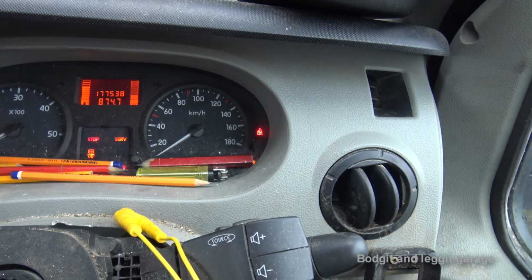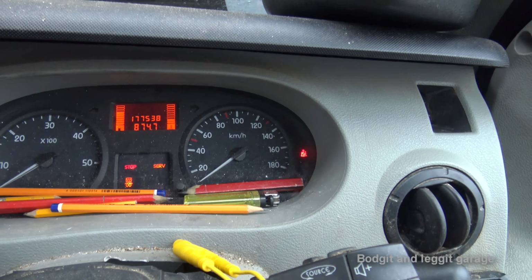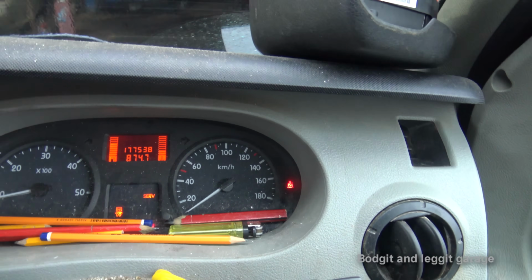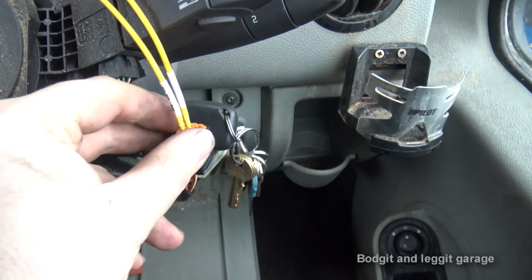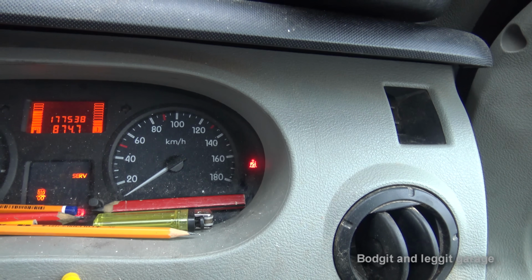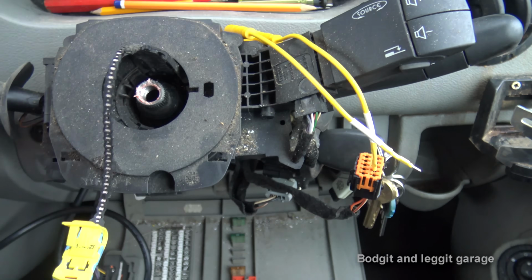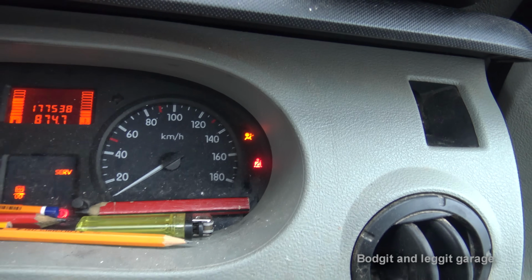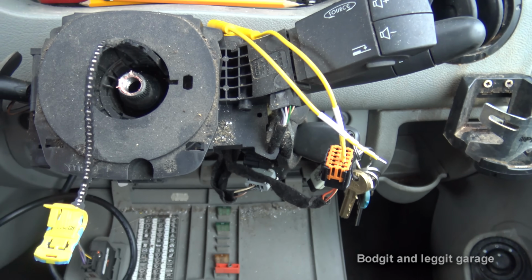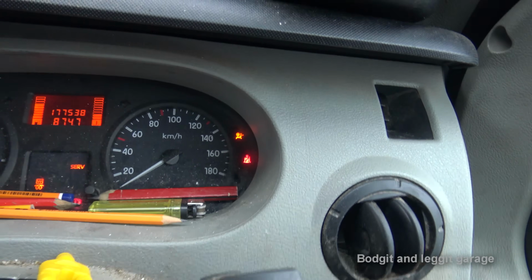And if you want to do one more test just to be 100% sure, let's just start this. What I'll do is I'll disconnect this from here, and the light should come back on, because the computer is going to think, oi, what you done? Where's my airbag? And there we go. So it's now recognized that something's wrong. Danger!